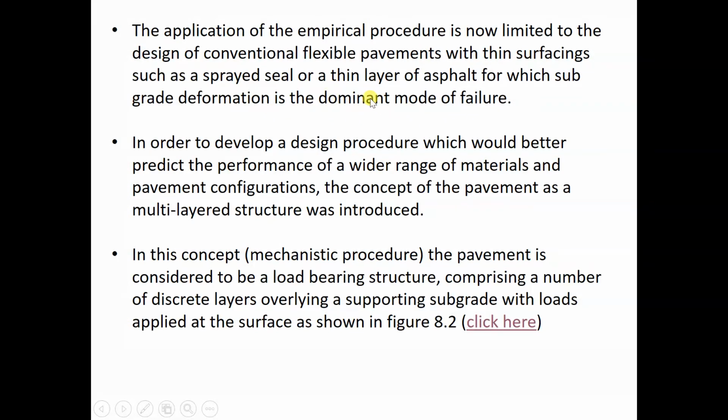So the empirical approach is only for road with a very thin surface layer, spray seal or thin layer of asphalt, and the subgrade deformation is the dominant mode of failure. So we don't consider any tensile failure, so that means that we don't consider any bound layer, only deal with the unbound layers.